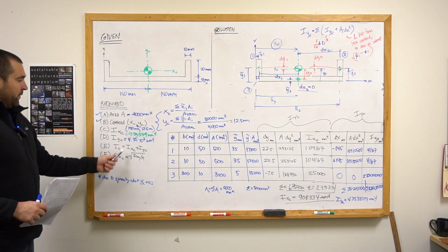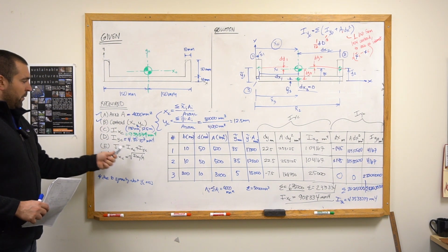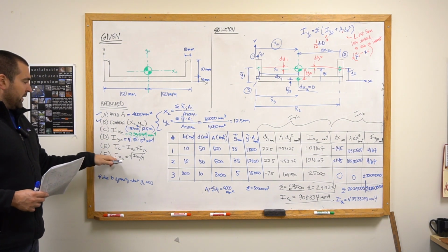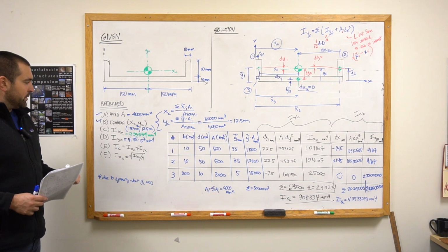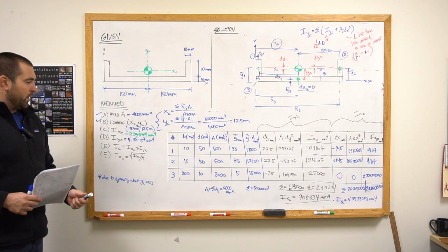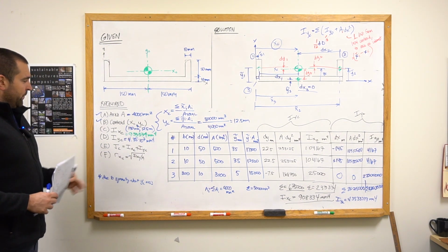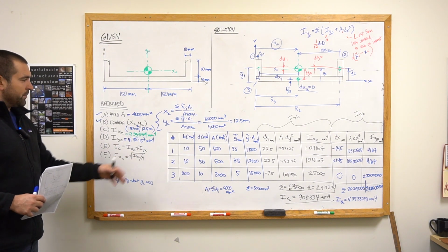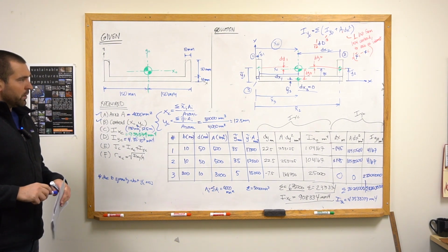And then, like we said, the trivial additional calculations would be to add these two together. That would give us the polar moment of inertia, which is used for torsion. And then to get the radius of gyration, I simply take the moment of inertia about the x sub c axis divided by the cross-sectional area, then take the radical of that. Like I said, these are not very calculation intensive steps, and so I'm just going to write down the formula, and you can review the calculation from the examples in the book.